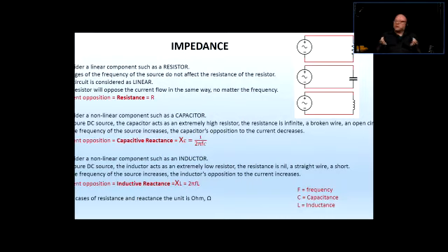So if you connect a pure DC to it, plus and minus, it is going to act as a short. It's going to act as a closed circuit. If you connect a pure DC to an inductor, you're going to burn it out if you don't have any resistor there, because it's going to be just connecting a straight wire from plus to minus.